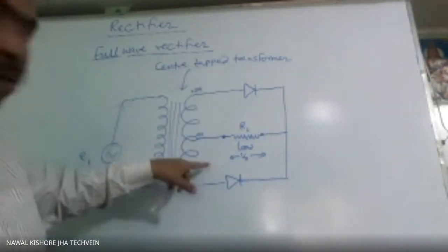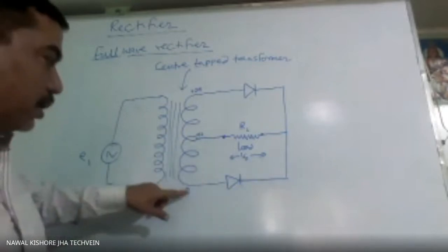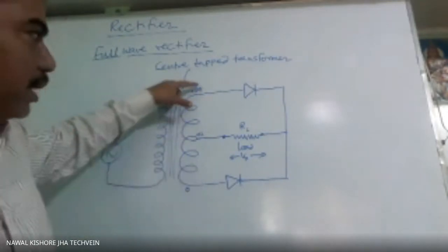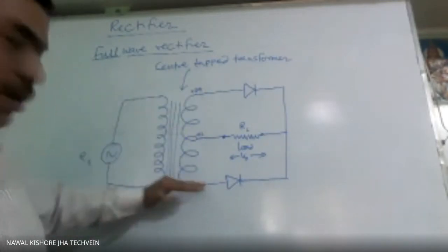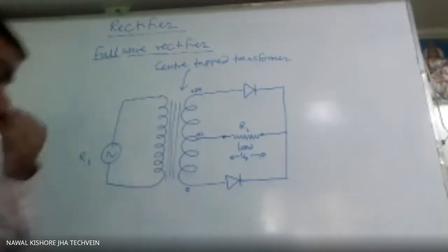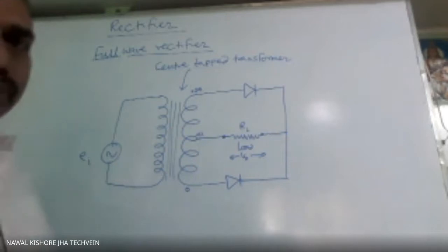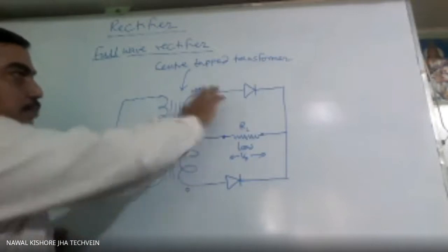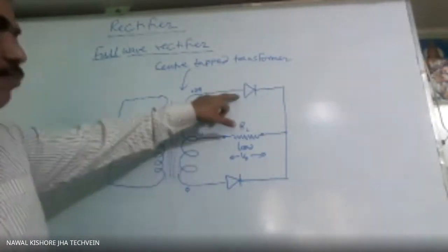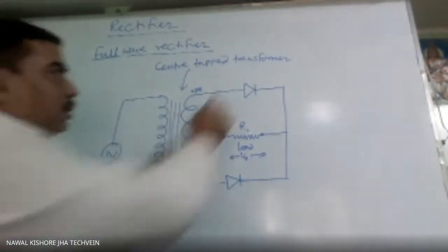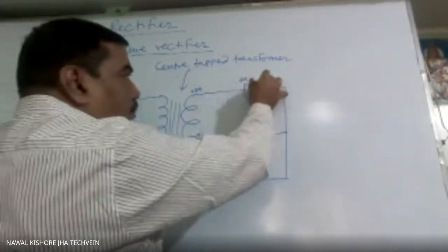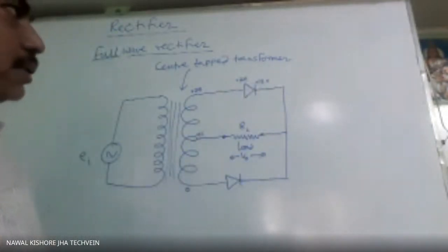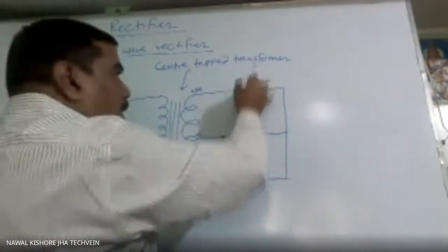If you have taken 24 volt output, or if you have taken 12 volt only, then here 0, then here will be 6, here will be 12. Reverse, minus 12, minus 6, 0. It will remain always at 0. Now what is happening? For the positive half cycle, this will be 0, this is 12. For this example, what is happening to this diode? This is at 24 volt and this is at 12 volt. Both are positive only. Is the diode forward biased or reverse biased? Yes.